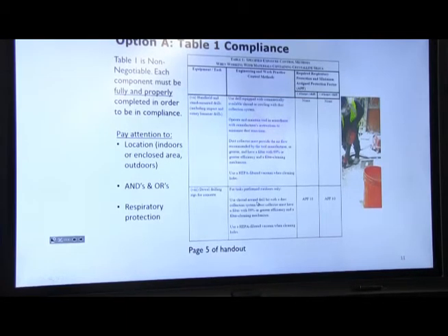And so for the handheld and stand-mounted drills, including impact and rotary hammer drills, if we use the engineering controls made by Milwaukee or Hilti or DeWalt, any of these companies, we can do our task without having to use respirators. And that's the name of the game here. We do not want to go to respirators. It's much better to use an engineering control versus PPE. It's always better to just use engineering instead of PPE.